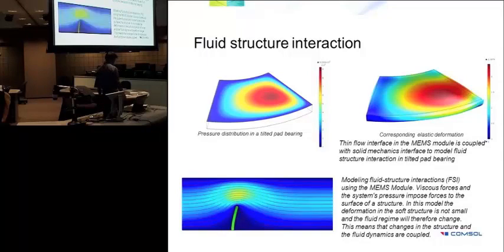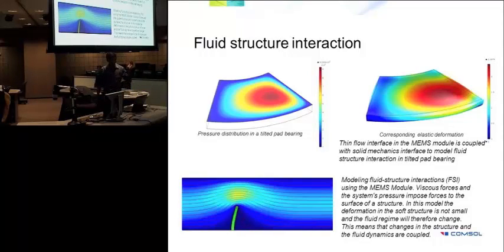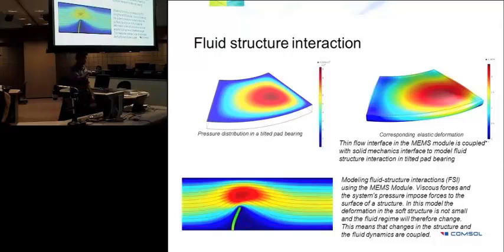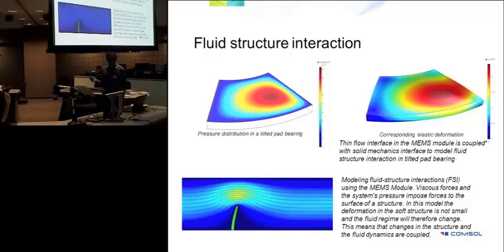The second example you must have seen in the morning session is fluid structure interaction. You have a fluid coming in from the left. It forces an obstacle and goes out the outlet. But the fluid stresses force the solid. So for the solid, the fluid stresses act as a boundary condition. However, when the solid deforms, the fluid domain also deforms, or the fluid domain changes.